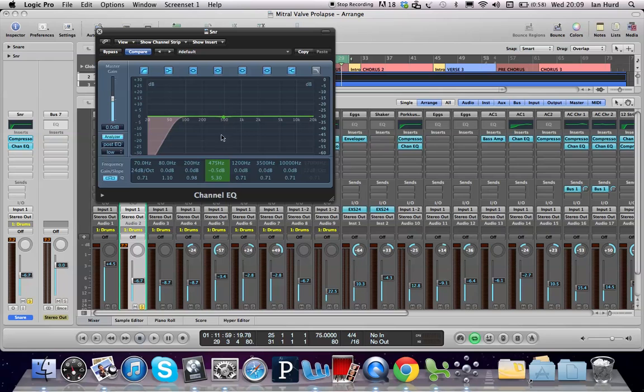So they're down here. And we can shape the selected EQ by dragging in the graphic display. So we're going to adjust the gain, we can drag vertically in the area of the EQ band. So we can just drag up like that anywhere in that area, and it drags the gain up or down accordingly.